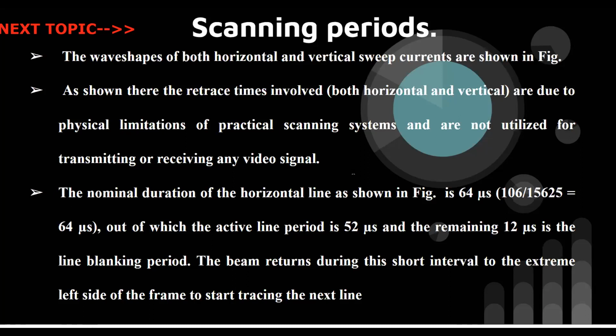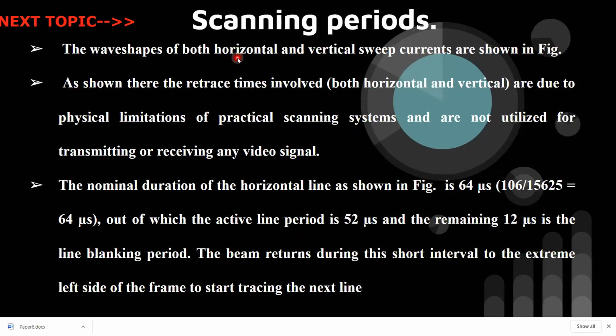They are the wave shapes of both horizontal and vertical circuits, which we will see in the next slide. For each period, as shown, there are retrace times involved in both horizontal and vertical due to the physical limitations of the practical scanning system, and these are not utilized for transmitting and receiving the video signal.